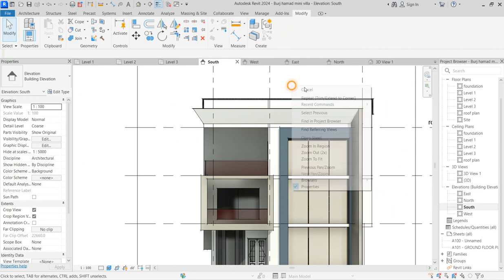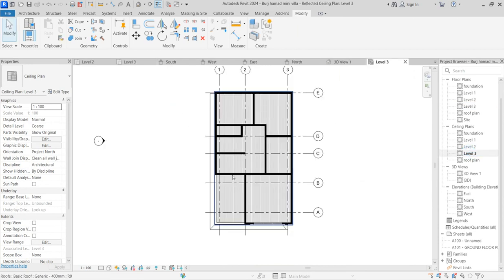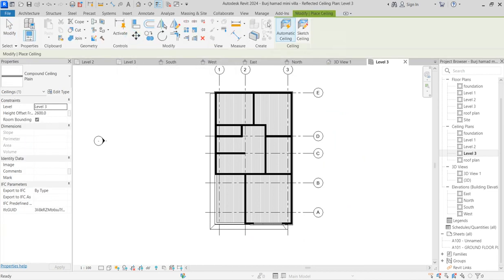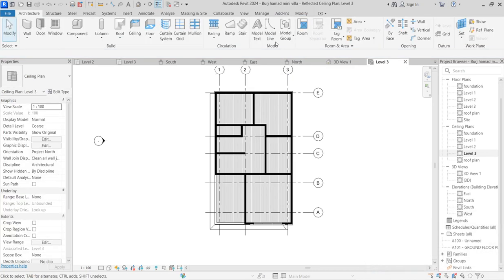The next thing we need to work on is to create a ceiling at level 3. So go to ceiling level in level 3. From there now what you do is that, because you want to attach some lighting and everything into that space, that will help you. Continue by going to ceiling. At the ceiling, just click on sketch, or pick first, pick automatic, click sketching.